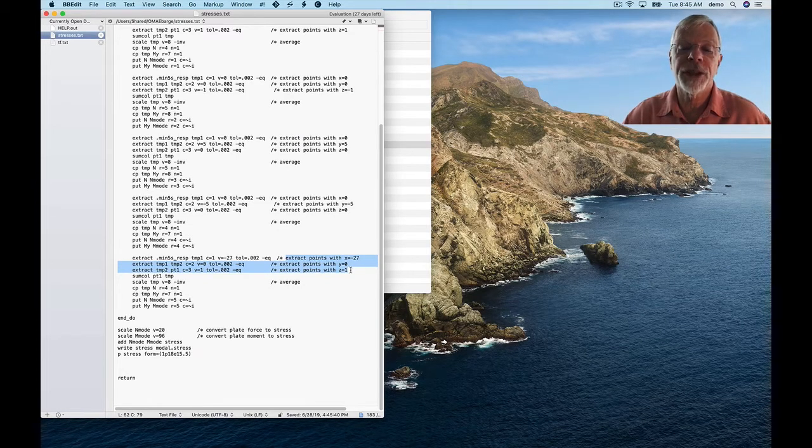response at minus 27, 0, 1. So that's along the center line at the top deck and at x equal to minus 27 meters. So that's towards the bow, if you will, because the wave is coming, if we're looking at a 0-degree wave heading, coming from the minus x-axis, propagating in the positive x direction. So this is towards the front, the quote-unquote front of the barge.